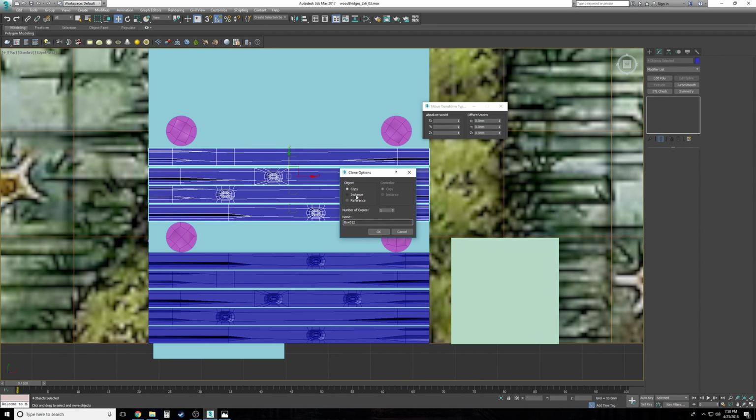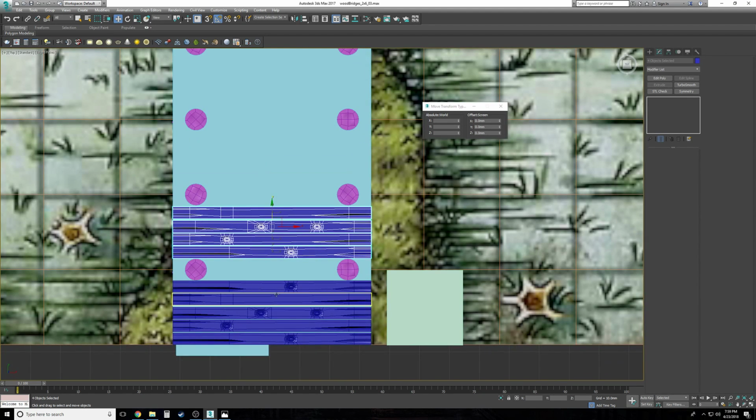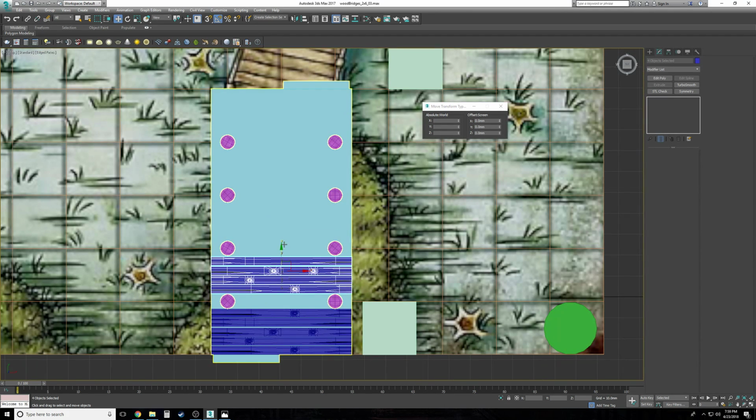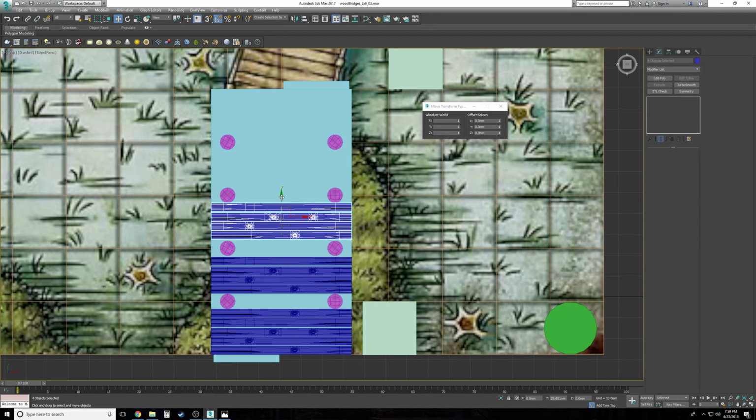That's the magic number. You want to instance these because they'll be the same. Now that you've copied these 3 over to here, you want these to be instances in case you want to just change these 3 and then the rest of them will change. And no one's going to know. You just keep copying these. Instance, you can rotate them.